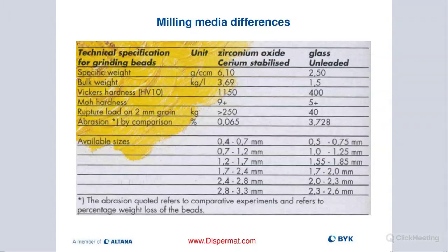Also, the hardness, right? You're only about a third the hardness of a good ceramic bead. So that kind of speaks volumes right there. So always try to get the better quality bead, because they're going to be heavier, giving you also higher kinetic energy, which would be really helpful when we're trying to break up these binding forces. So try to get beads that are heavy and ideally made of ceramic for that super hard surface.